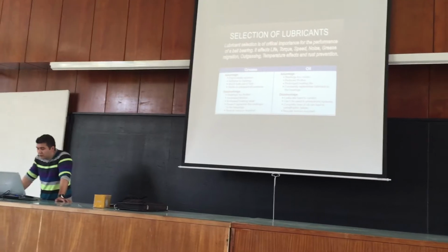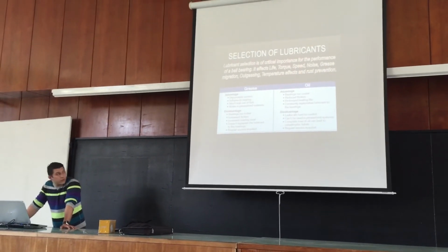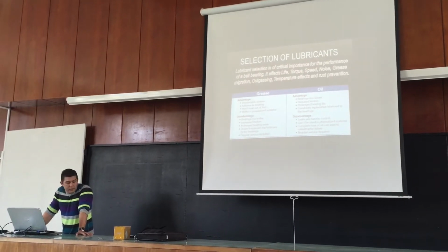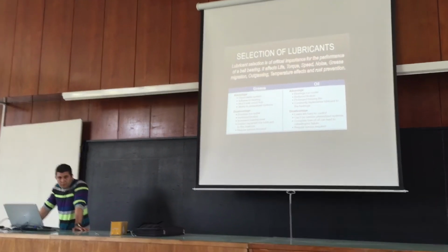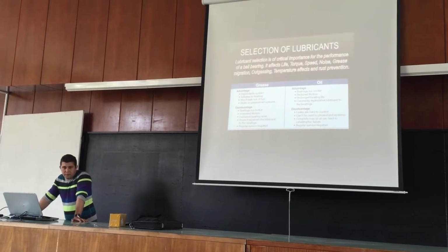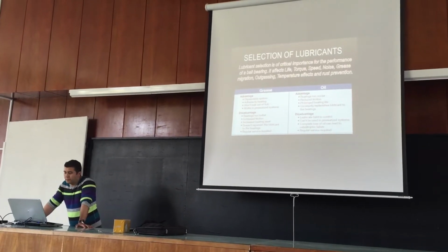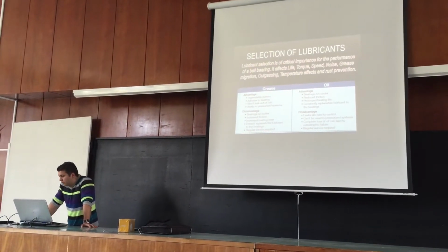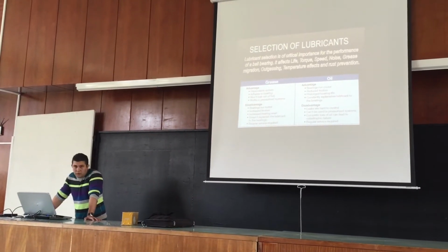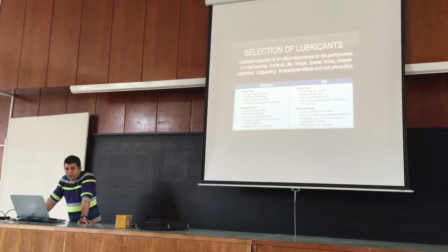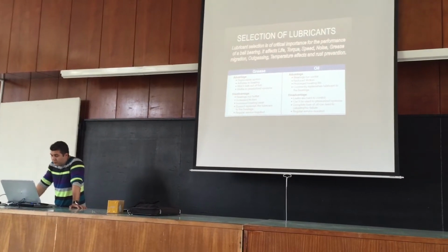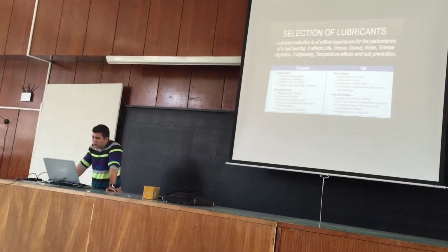If we can say for advantages of grease, they are a dependable system, adhere to the bearing, wouldn't leak out of the housing because they are a little bit thicker, and work in pressurized systems, which is a little bit more heavy duty. And if you talk about oil lubricant advantages, bearings run cooler, reduce friction, prolong bearing life, and constantly replenish lubricant to the bearings.